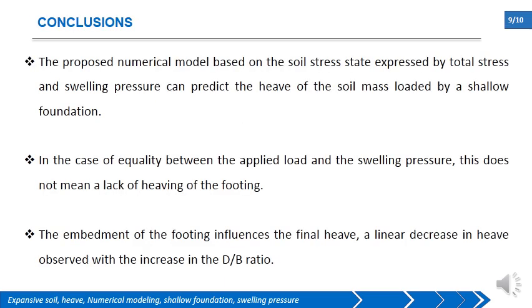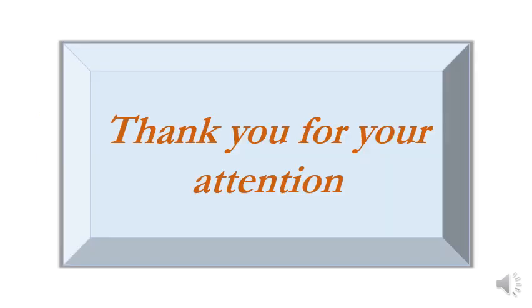In conclusion, it is important to note that the proposed numerical model, based on the soil stress state expressed by total stress and swelling pressure, can predict the heave of the soil mass loaded by a square shallow foundation. In the case of equality between the applied load and the swelling pressure, this does not mean a lack of heaving of the footing. The embedment of the footing influences the final heave. A linear decrease in heave is observed with the increase in the embedment. Thank you for your attention.